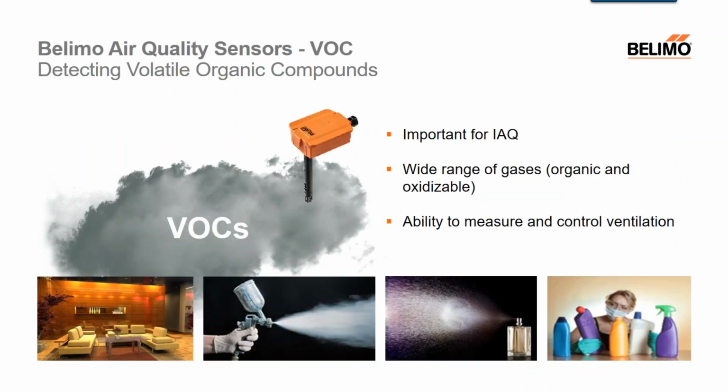Belimo also offers volatile organic compound sensors, VOC sensors. And the technology is also important for indoor air quality and demand control ventilation. The Belimo VOC sensors measure a wide range of gases based on heated catalyst principle and give us the ability to measure and control ventilation rates.